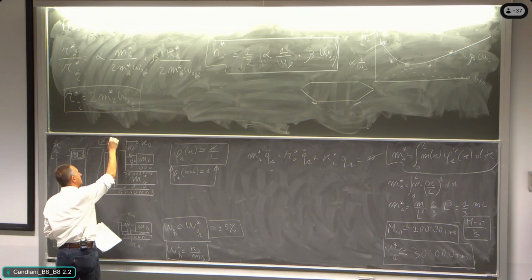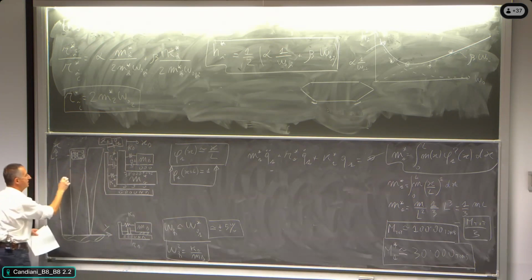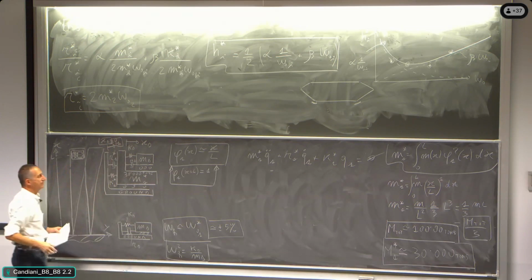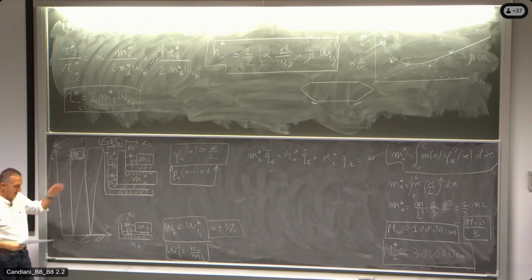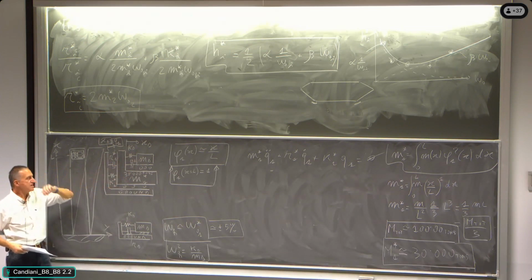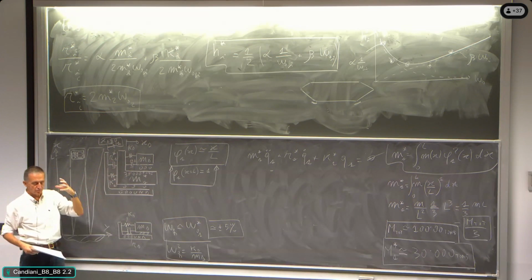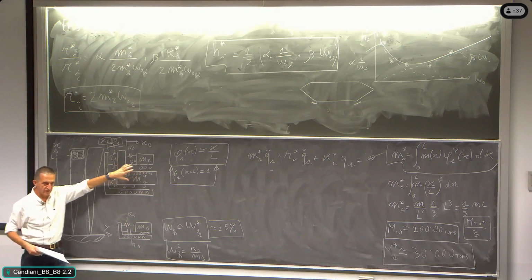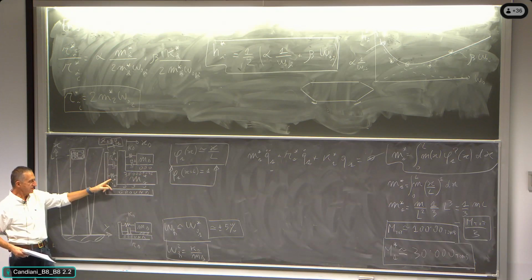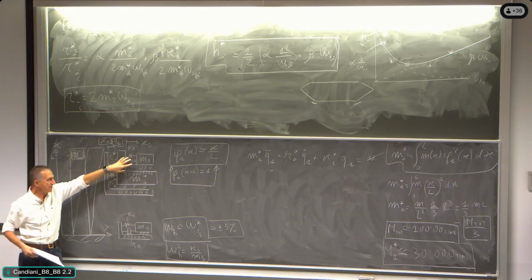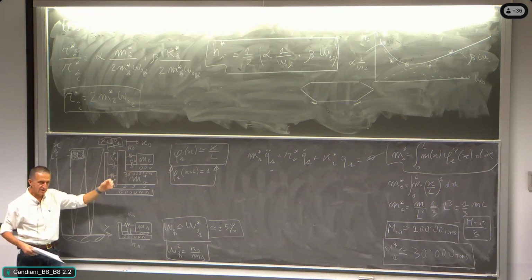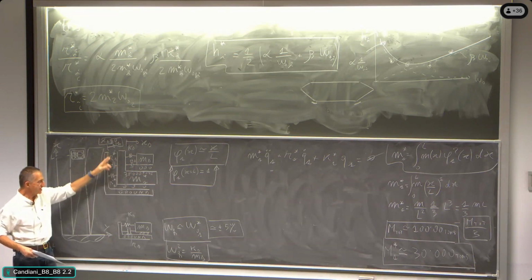So Q1 is the principal coordinate here, but then I write here Q1 is equivalent, totally equal to Q, and the equations are written as X1 and X damper. So, all right, in the equation I just would like to say that you have the total inertial forces that are counteracted by the stiffness here and the damping here. This gives an internal force to the system. So if my system is mass 1 plus mass damper, I have the total inertia and just those two forces.